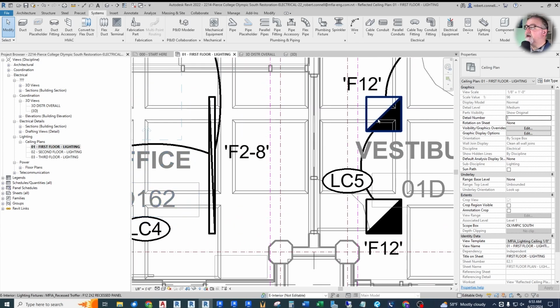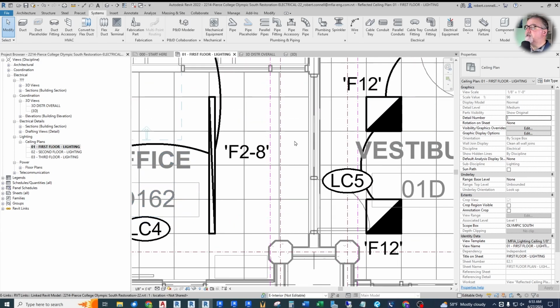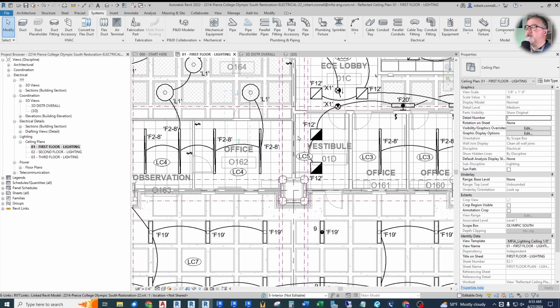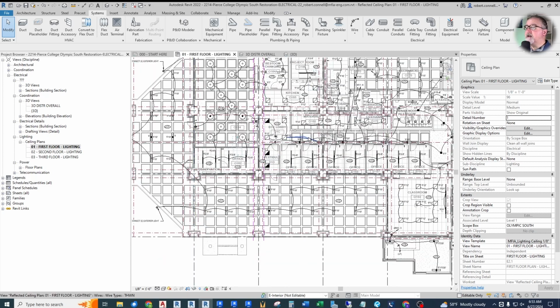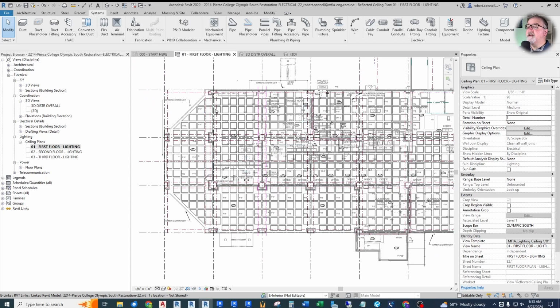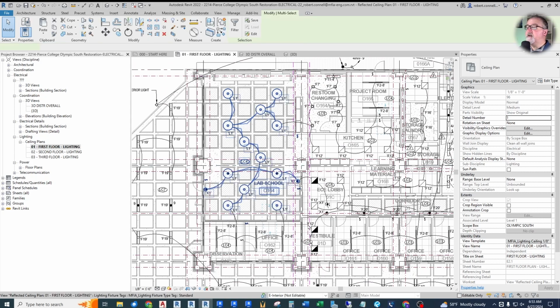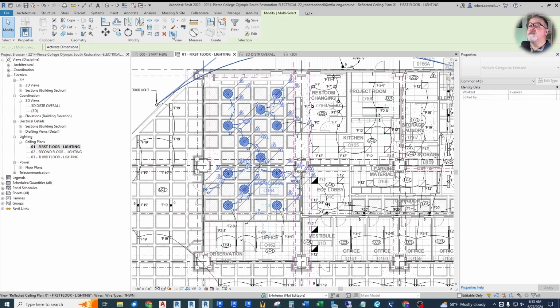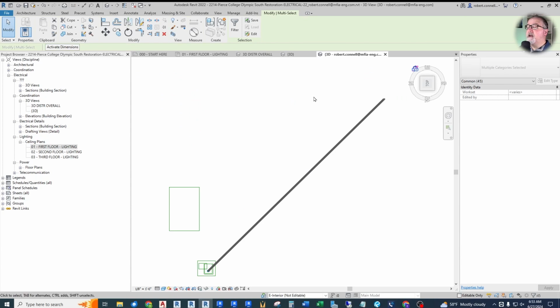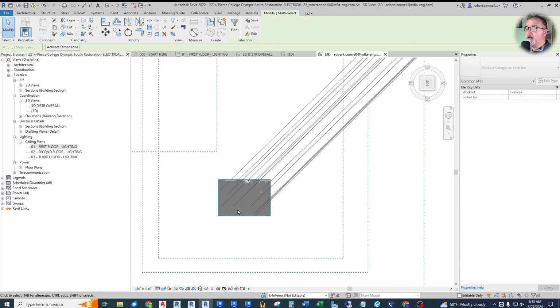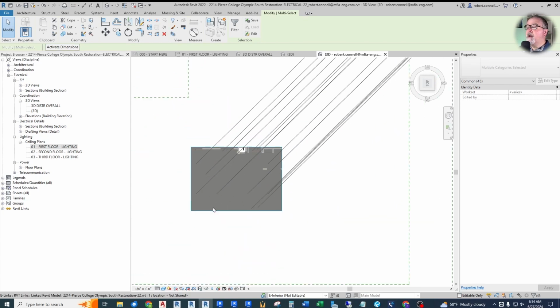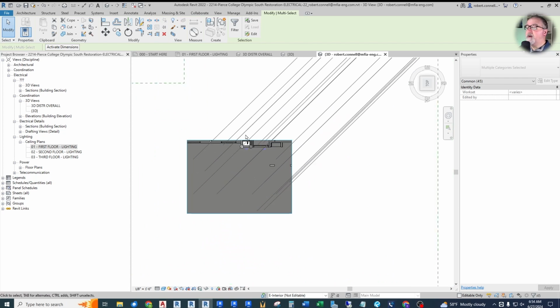But you can see some other lights. We have some other emergency lights that are dashed in for a recessed 2x2. So we have all kinds of lights. Now, if you want to know how this looks in 3D, let's take a look at this lab school room in 3 dimensions. And one thing we can do is we can hold our cursor down, highlight this area, and then up here under view, there's a neat little thing called selection box. You click on that, and you can see this gets huge, but it drew a box around that area.